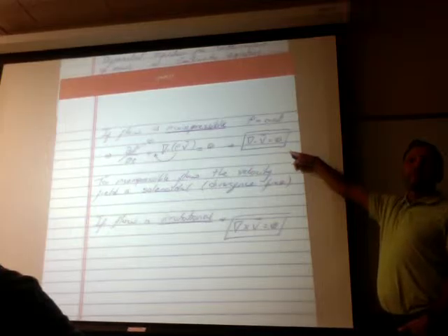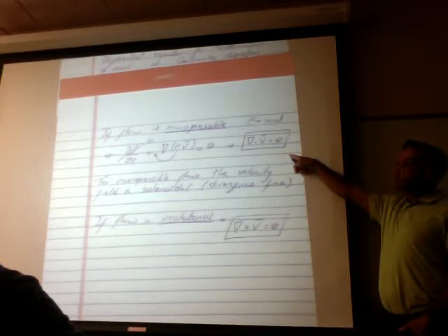This is a big assumption we're making here. The assumption of incompressibility on a vector field is not far-fetched. Again, if it's a liquid, that's always the case. If it's a gas and it flows below 30% of the speed of sound, then that's also the case, always. So this is always true. We don't need to make any assumptions unless we have very fast flows of a compressible fluid.